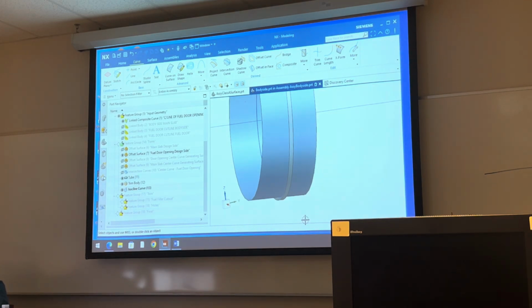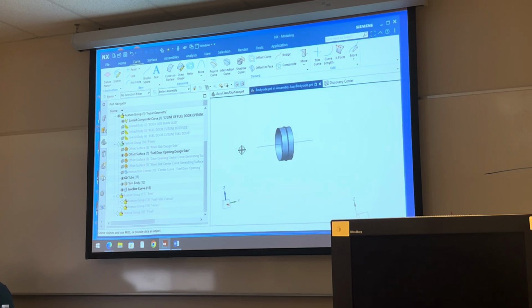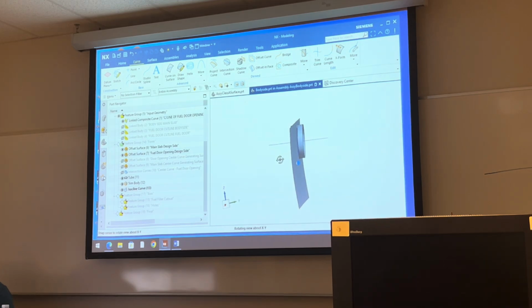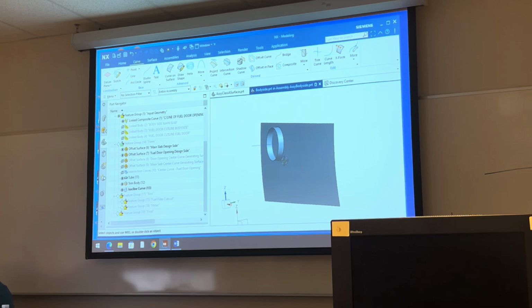Because if you stamp the part with an exactly cylindrical pocket, it will either tear or it'll lock up. Right? When you stamp it apart, it's got to open up. It's got to be an open angle when you stamp it. Let me show them. Nice slab there. We're gonna stamp it from this side, stamp it and pull the die back, right? So it's gotta be bigger in this orientation. Instead of a cylinder there, it's really gonna be a cone. It's gonna be bigger on this side, smaller on that side, because the bottom of the pocket's gonna be this side, okay? So we're not gonna use that cylinder.